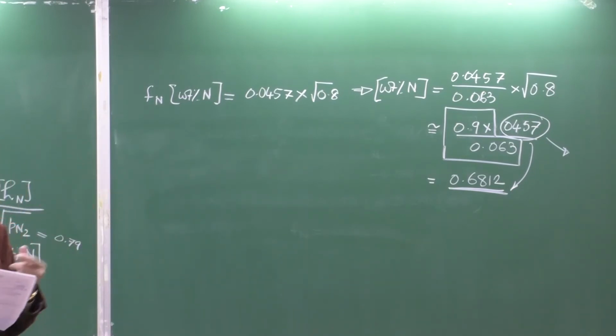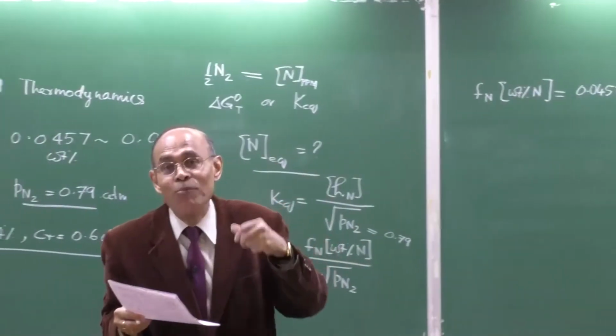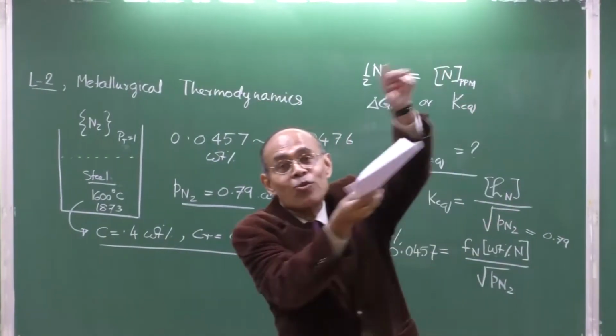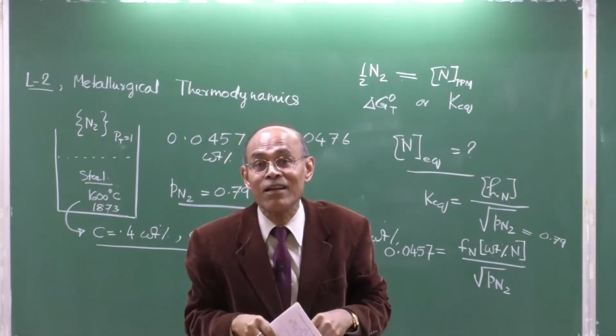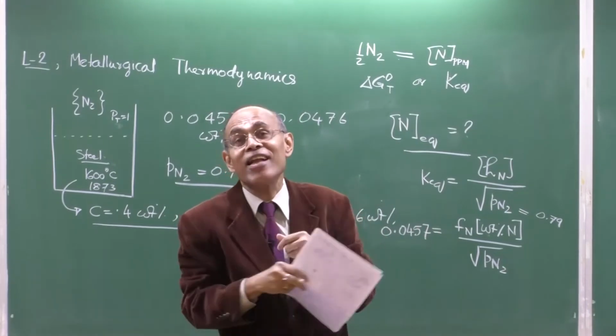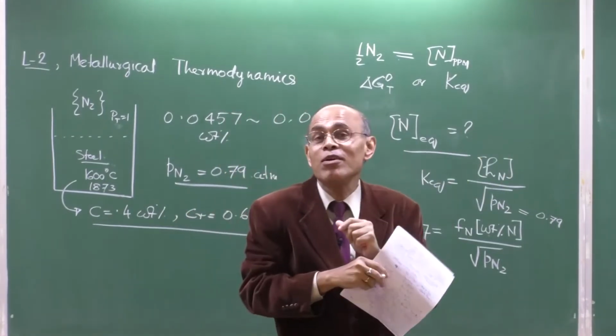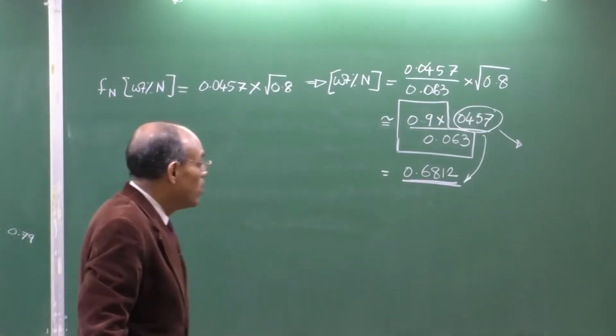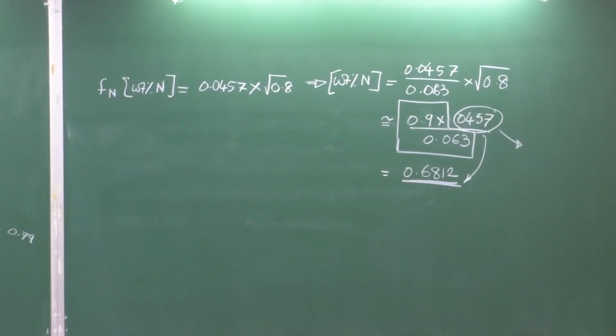For example, it tells us that if you tap an alloy steel from a furnace, which will pass through the ambient atmosphere and fall into a ladle, the chance of nitrogen pickup from the atmosphere is going to be significantly larger than in the case of plain carbon steel, because of the enhanced equilibrium solubility of nitrogen in alloy steel.